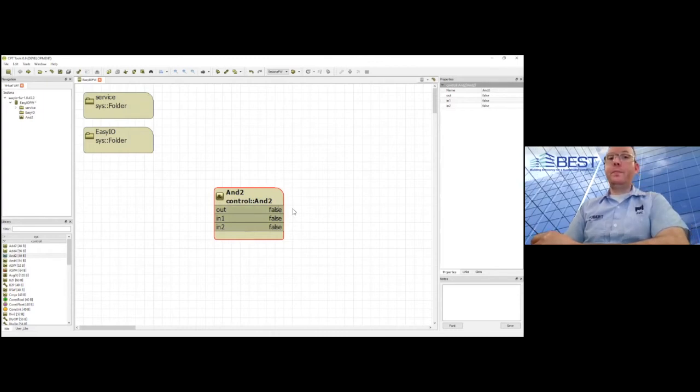Okay. And can have more than two Boolean inputs. It doesn't change its function. You have to be careful how you apply it if you're doing certain things though. But technically you could have an AND block that had 50 Boolean inputs. I would feel sorry for you, but you could do it. Okay. But what AND does is AND says input 1 must be true and input 2 must be true to get a true output.